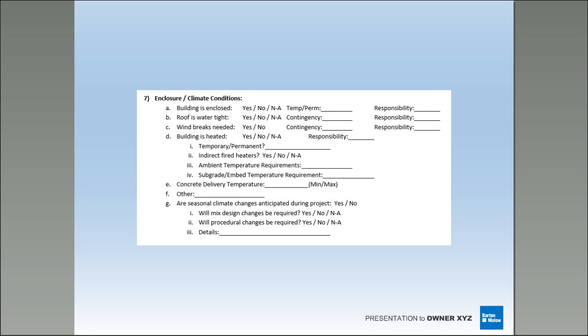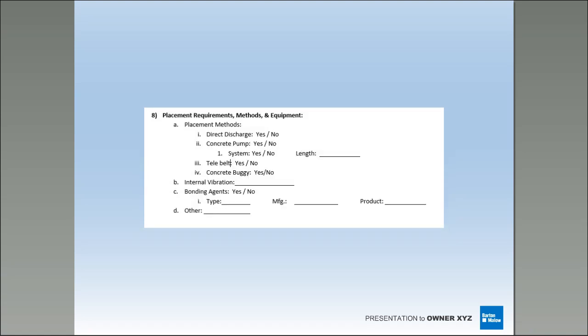You don't want a big color difference. You don't want a big gloss or shine reflectivity difference, and a lot of that's going to be weighed out in your mix design. So again, if it comes up in a pre-pour that your place finish contractor is going to make some mix changes because of seasons, whether it's hot climate or cold climate, you need to know what the changes are and how they're going to affect the aesthetics of that mix at the end. All right?